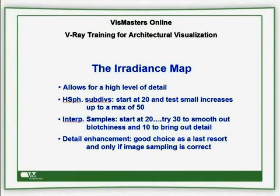Some things to remember from Module 1: the hemispheric subdivisions value plays a critical role in the quality of your Radiance map samples. 20 is a good value to start with, and you should experiment with small increases up to a maximum of 50. To smooth out any blotchiness in your samples, try increasing the interpolation samples up to a value like 30. To reduce the smoothing effect and bring out detail, you could try reducing this value to 10.